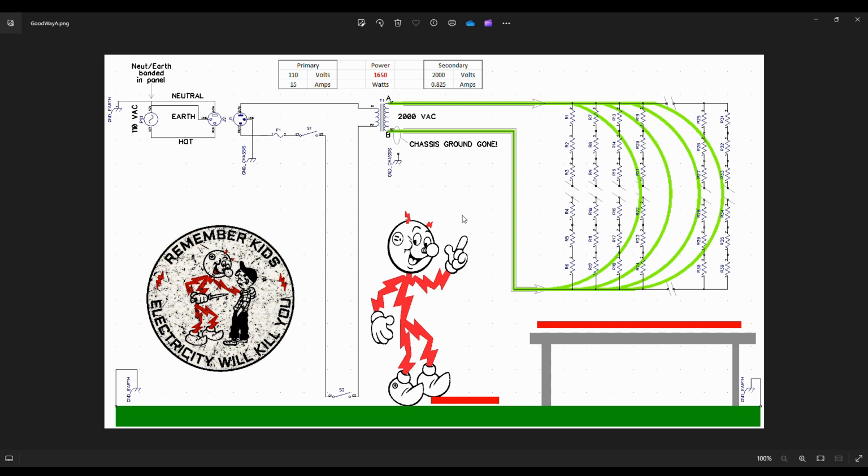And I'm going to also throw down the gauntlet here. If anybody who thinks they knows better, who's been doing this for years without an accident, those kind of clowns can come to me and make the argument that, oh, I think this terminal B should be connected to chassis ground because that's the way it's in the microwave, or whatever excuse you have. Bring it on. We'll have that debate in public. That's how wrong you are about wanting to have this chassis ground here.